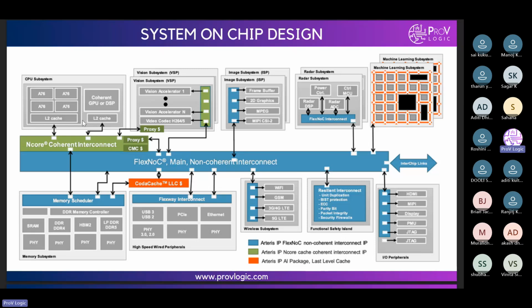Okay, so on the processor side we use AXI, but on the low speed side AXI will not work because it works at a very high speed. Low speed means frequency mismatches will be there. The data will not communicate properly, right? So for that purpose, on the low speed side we use APB, and we will try how we can transfer high speed data to low speed data. That's what we need to learn majorly. Okay.